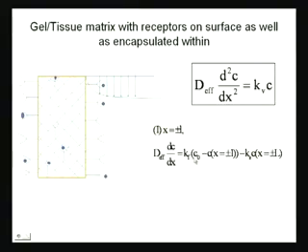Let me show you and then it will be clearer. So, this that you see over here on the right hand side, Kf C naught minus Cs, forget this term over here, don't worry about this term right now. Let us look at this term alone, C naught minus C. This is your total driving force, right. C naught minus C is the total driving force times the Kf, which is the mass transfer coefficient, that should be equal to the amount of flux that is coming in. Fine. Now, what is this term doing over here?